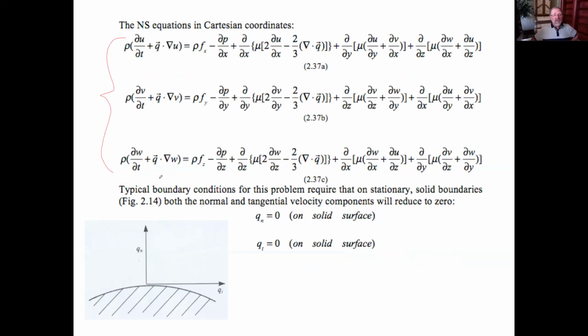I mentioned the no-slip boundary condition. So the boundary condition on a solid surface is going to be velocity normal is 0, which is logical. And the velocity tangential, which is going to be, say, y and z direction, is also 0. These are typical boundary conditions. Now, this is a partial differential equation, and undergraduate students never hear about that. So please excuse me, but we jumped 2 levels, and we're presenting equations which you never studied in calculus. Then on top of everything, there's no solution to that one. So it's pretty complicated.